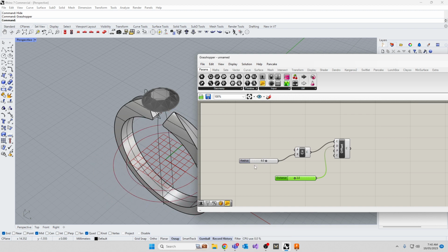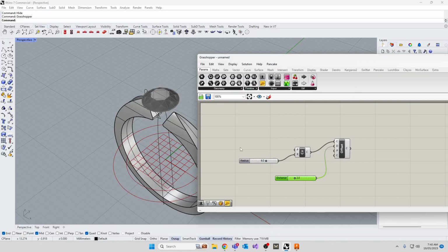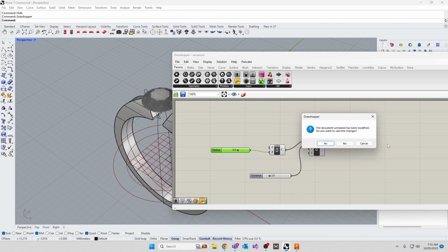I can do an extrusion. This is proper parametric modeling, the same as you saw inside here. So this has just got a nice, neat direction of commands. In Rhino, it's got these kind of spaghetti balls that you can come back and edit live. So I'm going to close that for now. Generally speaking, for design, you don't use this. There are instances if you're making a range of jewelry where you have to change finger sizes, you might use it. Generally speaking, you don't use it.